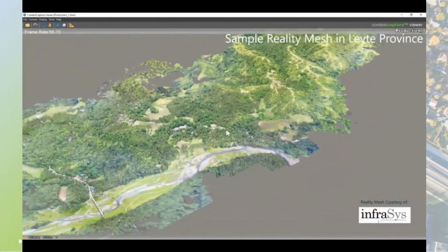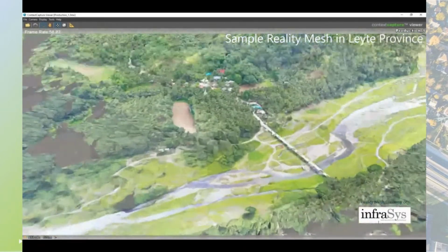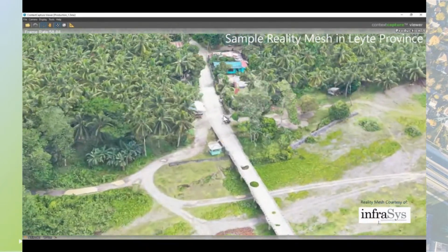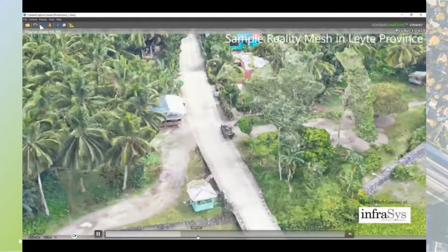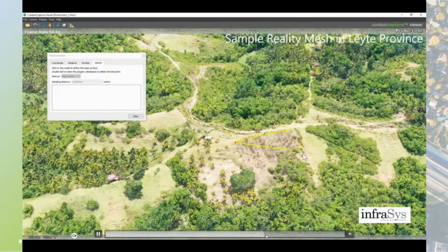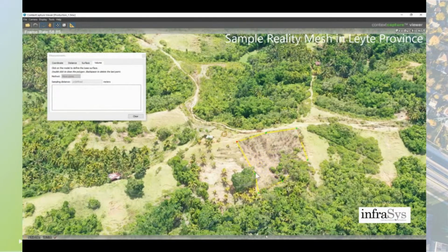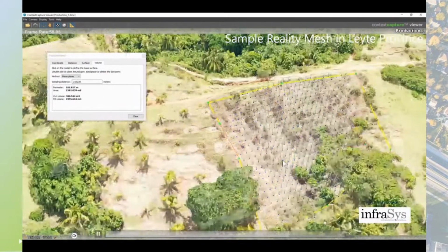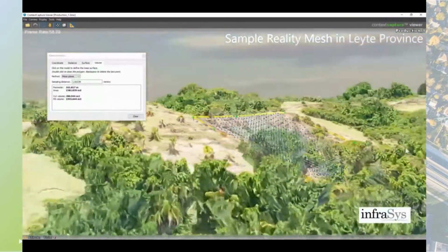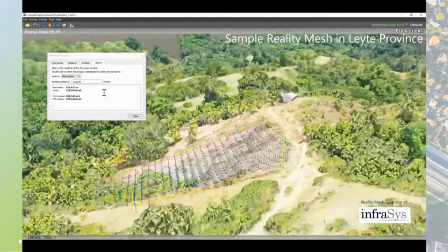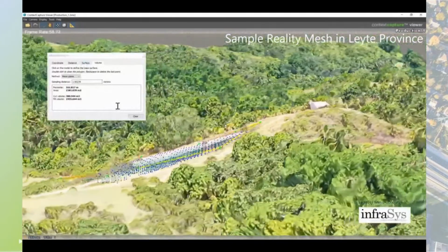And then you can start from here in ConceptStation, or even in other solutions of Bentley Systems, like for instance OpenRoads Designer, so that you can generate a model out of it, right? Or a terrain out of it. And with the reality mesh itself, you could already do measurements, volume calculation, surface area calculation, and so on. So you have a tool, an information, that you could take into not only your conceptual modeling but also your detailed design.